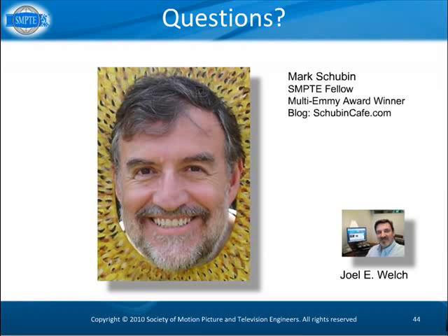John Yeller asks, what codecs are there that exploit the presumably very high correlation between left and right images to achieve high coding gains? There are some. You might want to look at TD Vision. They're one of the ones that's been pushing that. But I think all of the encoder manufacturers are looking forward to something like a 2D plus delta, which is what's being discussed. There was a discussion of 2D plus depth, where you would take, say, the left eye image and you would add depth information, but that's kind of difficult to code. But 2D plus delta is basically what you're talking about, very limited difference between the signals, and therefore that works well in codecs.